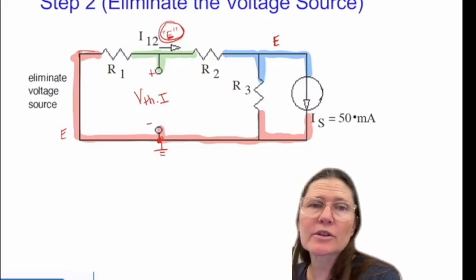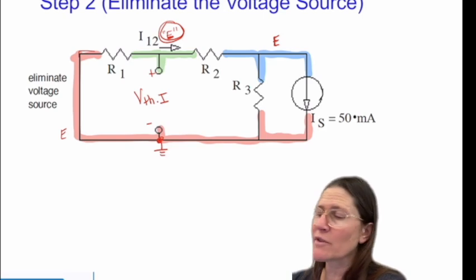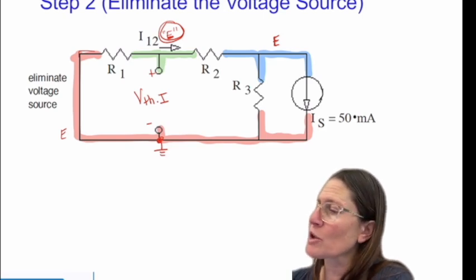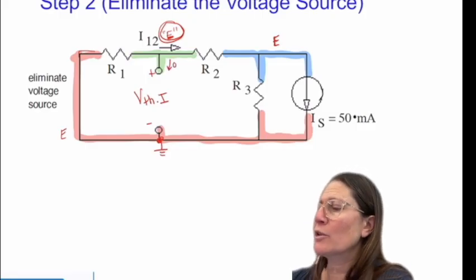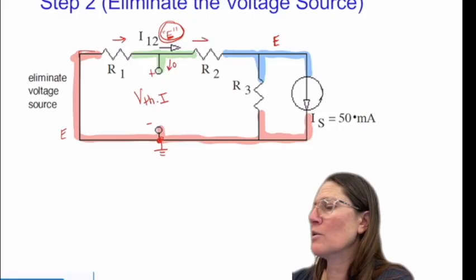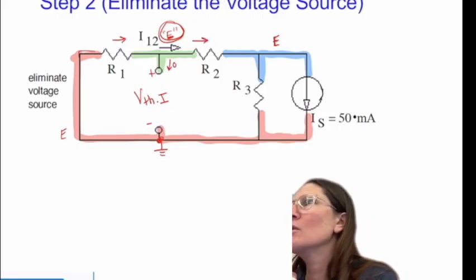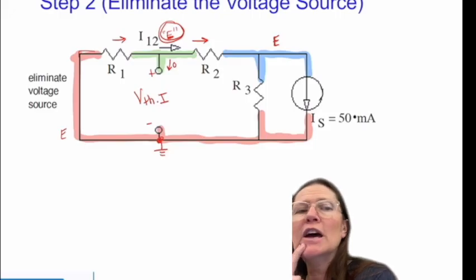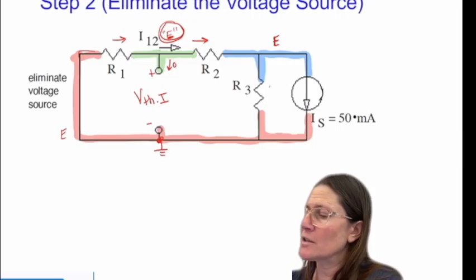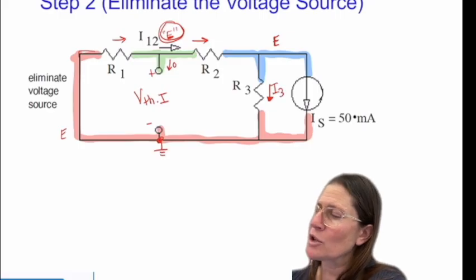Current that looks like there's 2 branches. Even though this is extraordinary, there's no current flow that's going to go in that wire. So the same current is going to go in each of those. So looking at that, I have one current in between R1 and R2. I have a different current that's going to go through here, but there's only resistors in there.